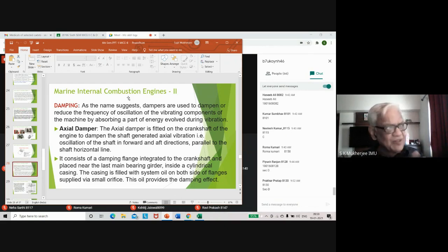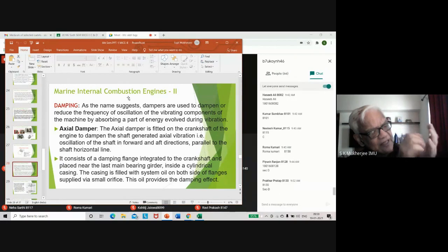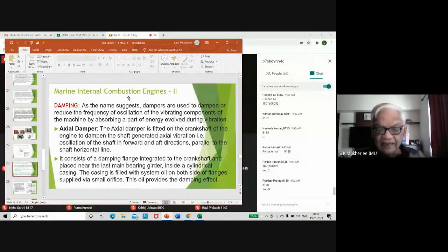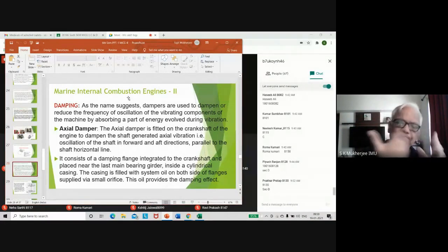You see, there are times when the clamps which are holding the pipes in place become loose because they are also vibrating. And if they vibrate and become loose, the entire pipe starts vibrating inside. Sometimes you cannot hear it, sometimes you cannot see it. But one fine day you suddenly find the pipe has ruptured and oil is leaking out from there. A small leak. And you look and you find the pipe has been hitting the support on which it is clamped, and that place has been worn out to the point where a crack has emerged, and from that crack oil has started shooting out.